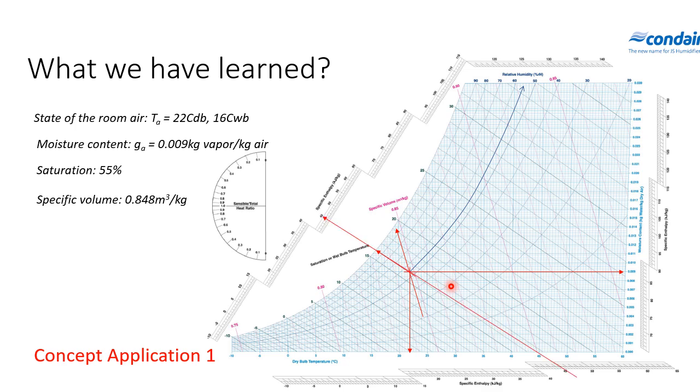Right, now let's carry on further. We draw a line from here to there, let this cross this point, and that point is about 45 kilojoule per kilogram. What's this? This is the specific enthalpy, right? So therefore, specific enthalpy HA equals 45. Enthalpy is 45 kilojoule per kilogram.